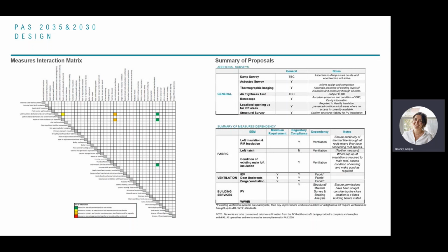It's really important to understand where the damp is coming from. If you've got a damp building fabric, you should not be implementing any energy efficiency measures. First of all, you need to make sure that property is in a good state. By increasing air tightness, you are likely to exaggerate the damp problems inside.